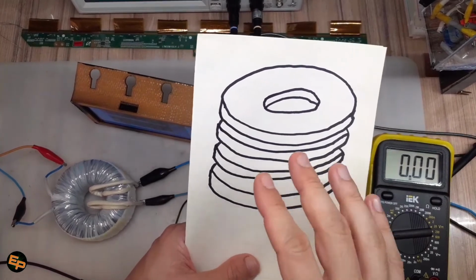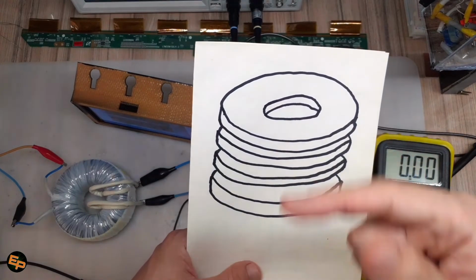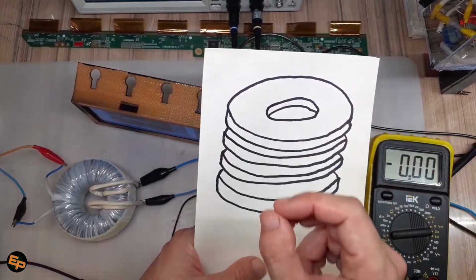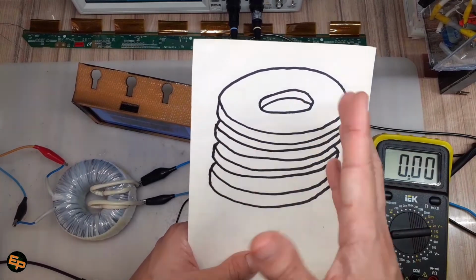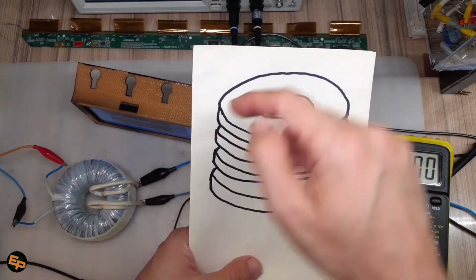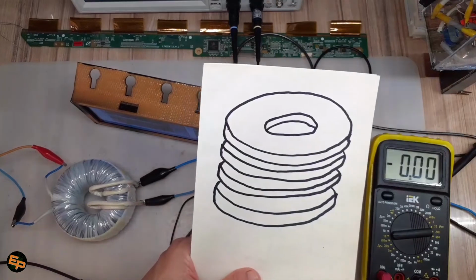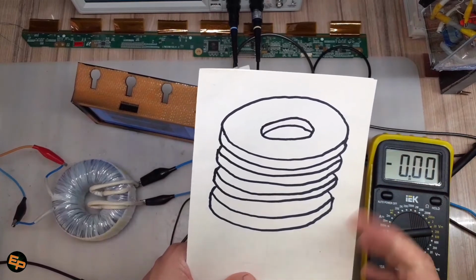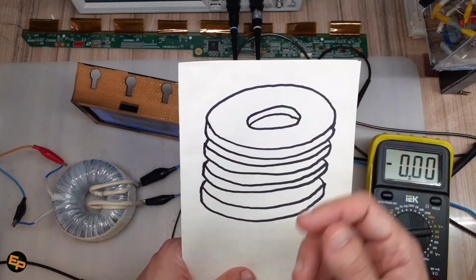The wire should not be too thick, because then it will occupy too big a space and you won't be able to give as many turns. And also, we're not looking at drawing significant current out of the coil here, right? We only care for the voltage, because the voltage is proportional to the current that goes in the conductor inside the toroidal core. So you can easily choose the thinnest wire that you have.